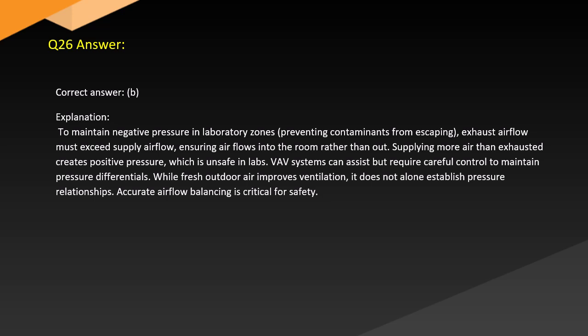Supplying more air than exhausted creates positive pressure, which is unsafe in labs. Variable air volume systems can assist, but require careful control to maintain pressure differentials. While fresh outdoor air improves ventilation, it does not alone establish pressure relationships. Accurate airflow balancing is critical for safety.